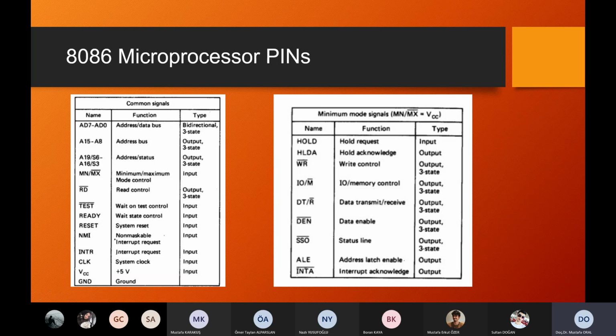If it's a memory operation, it should be 0, the signal should be 0. And if you don't say that, it will be active in 1 in both cases, but that is impossible, because if it is 1, it should be in input output mode. If it is 0, it should be in memory operation mode. So you have to write the bars. Definitely you have to write them.